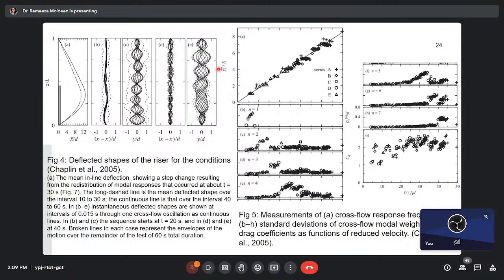And this is the vortex shedding frequency with respect to the natural frequency. So once we know the vortex shedding frequency of particular dimensions, that is the stiffness and how it is behaving, then we can keep the natural frequency away from the vortex shedding frequency.